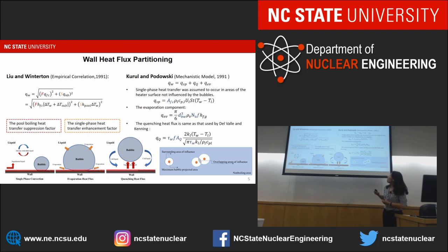And as the understanding of the boiling phenomenon deepened, this type of mechanistic model has been used in the multi-phase flow calculations. The wall heat flux here is decoupled into three parts according to the heat transfer mechanism: the single phase heat transfer, the evaporation component, and the quenching effect.